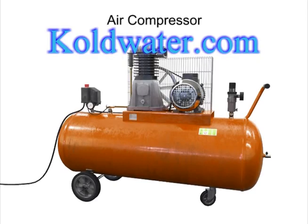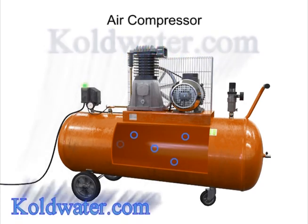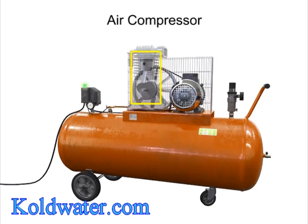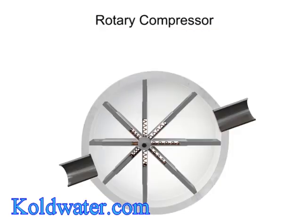An air compressor is a device which takes input mechanical power, typically from a motor, and converts it to fluid air power. The compressed air can be stored for later use in compressed air tanks, or it can be transferred via pipes to a point of use. Compressors with a piston as the compressing element are called reciprocating compressors. Compressors can also be made with vanes or impellers. These types of compressors are called rotary compressors.